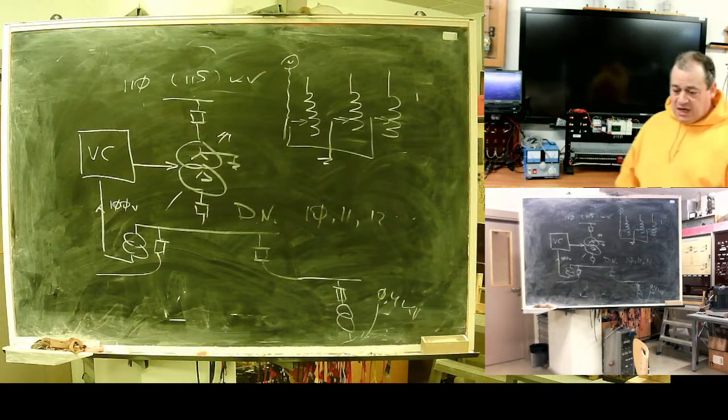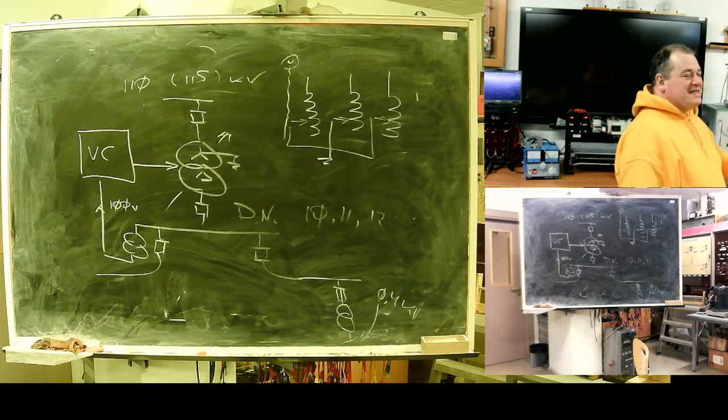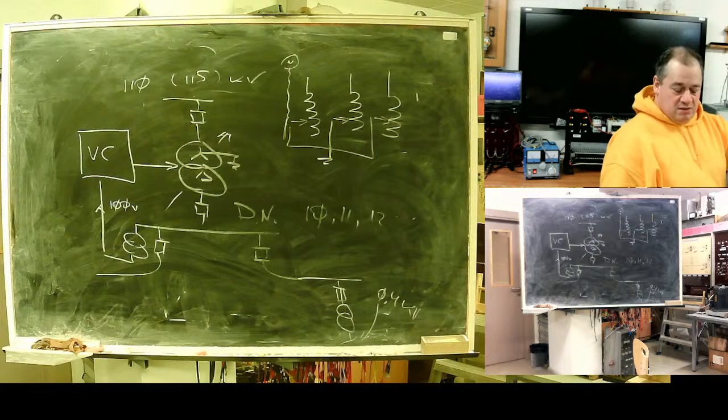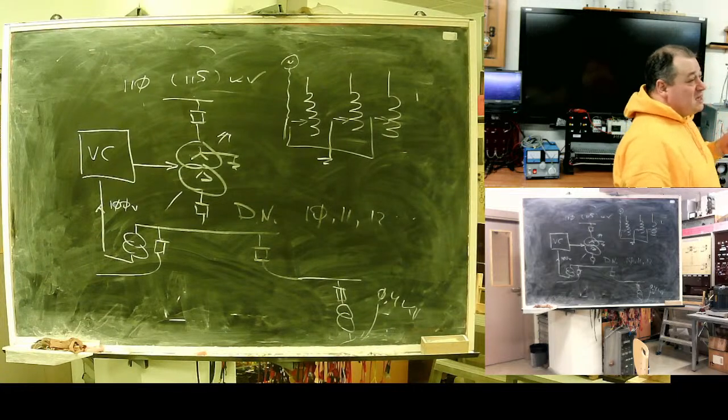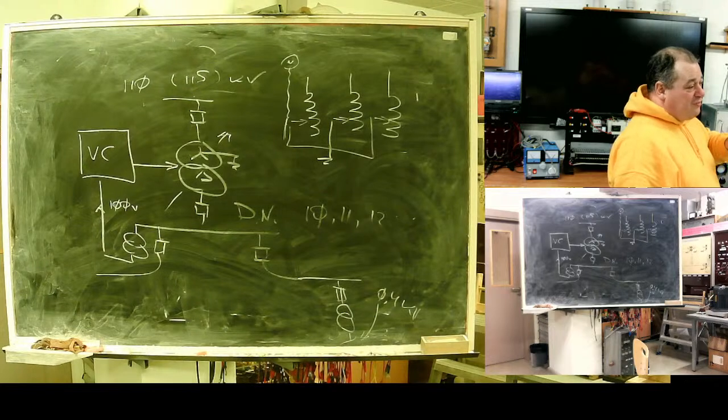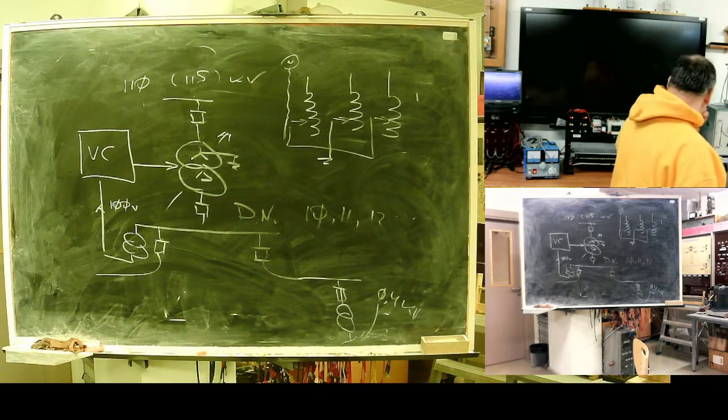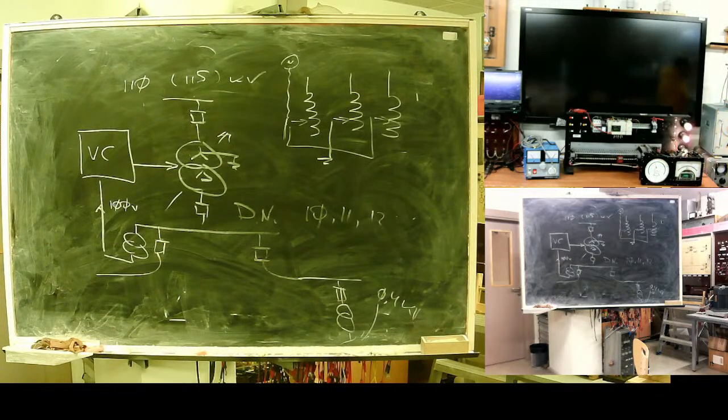It's not 100% precise because it's not a continuous change. It can only change by a tap. It will have a dead zone, something like 1.25, 1.5, sometimes 1%.